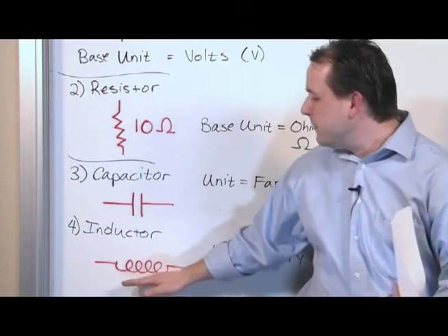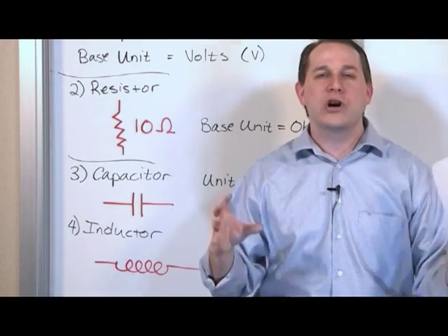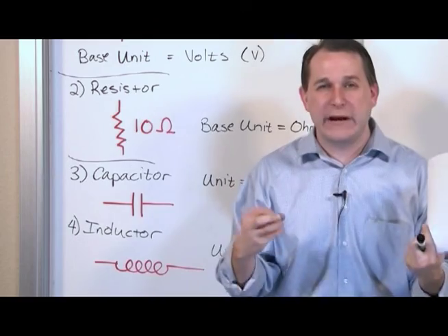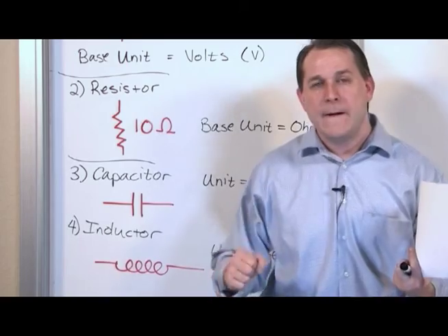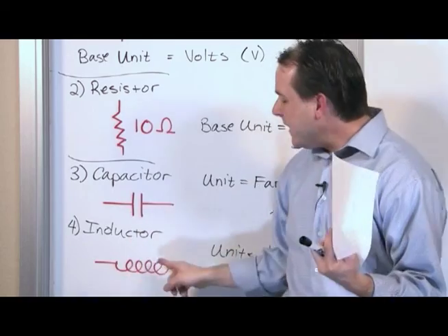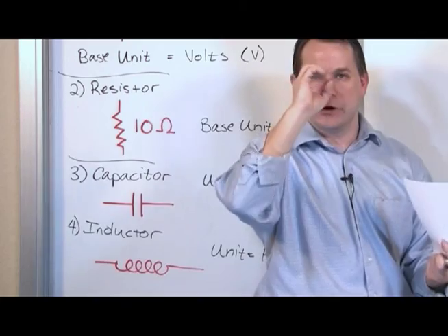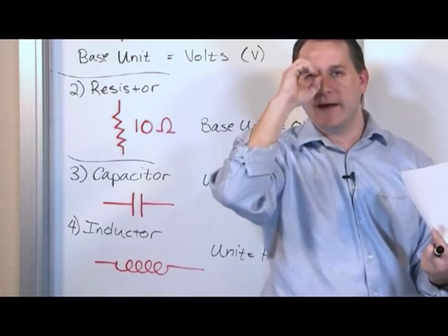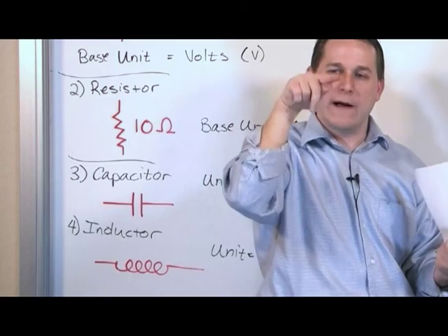So what we try to do when we construct an inductor, and this is important, is make a device that will concentrate that magnetic field and make it stronger so that we can store even more energy inside that magnetic field. And that is exactly what an inductor actually does. Because if you take that wire and you look at its magnetic field, it goes around the wire. But if you take a wire and you coil it up like this, think of a cylinder coming from me to you, and I take a wire and I wrap it around the cylinder, like a paper towel tube or some kind of pencil maybe, and I wrap a tight wire around this cylinder.